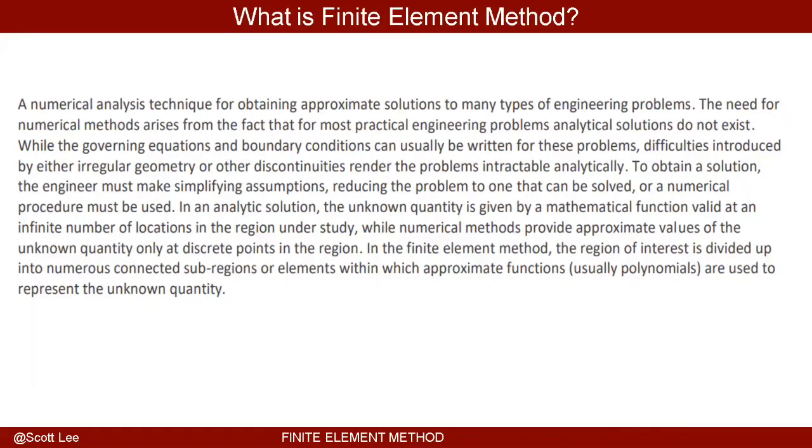But basically, if I were to simplify what the finite element method is in a couple of sentences, all it is saying is that you have a complex domain, and that complex domain theoretically has an infinite number of degrees of freedom. So how can you assess a structure when it has an infinite number of degrees of freedom within the domain?